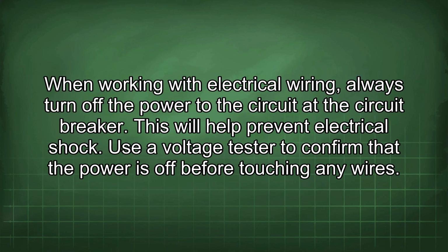When working with electrical wiring, always turn off the power to the circuit at the circuit breaker. This will help prevent electrical shock. Use a voltage tester to confirm that the power is off before touching any wires.